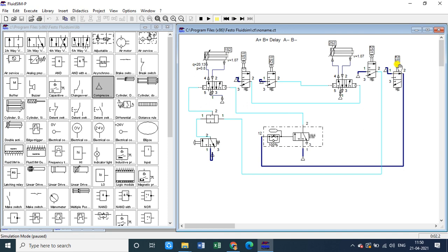So when it is getting pressed, the left side block will become active, and the air will come out from that valve, and it will go to the input port of the time delay valve. It has a total of two inputs. One is from the air service unit, the second is from the pilot operated valve or simple limit switch. Then how it will flow, that we will see.